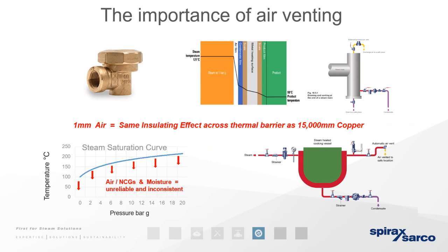First and foremost, it will become reabsorbed back into the condensate and turn into carbonic acid. This will cause erosion, it will cause corrosion, my apologies, but also means that this carbonic acid is returned to the feed tank. It will need to be treated with much more chemicals, and most likely you will have more TDS blowdown.